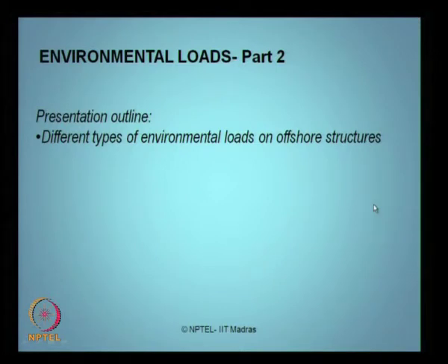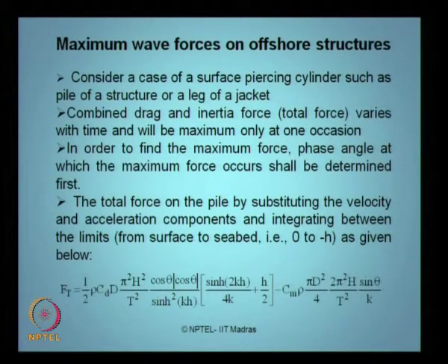In the last lecture we discussed the calculation of wind forces and wave forces. Now, interestingly, we must know how to compute the maximum wave force on an offshore structure. The question comes: what do you understand by the maximum wave force? Let us consider a surface piercing cylinder, such as a pile of a structure or a leg of a jacket platform. The combined drag and inertia forces, which we call the total force, vary with respect to time and will be maximum only at one specific occasion.